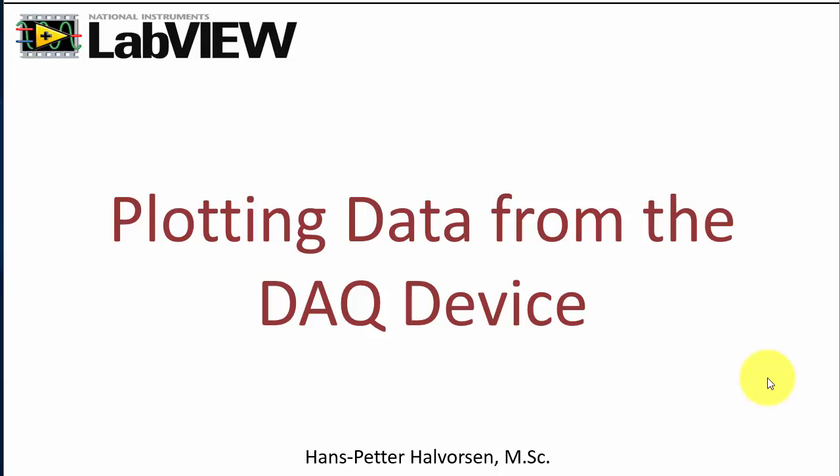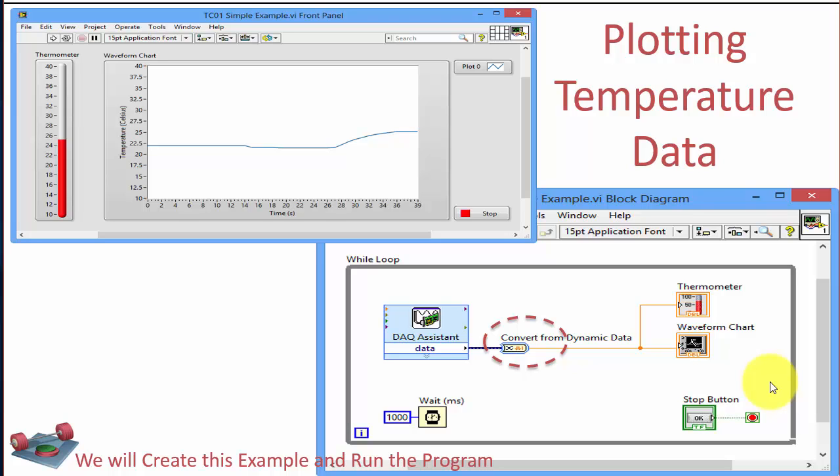Next we will learn to plot data from the DAQ device. We will learn to create this simple example. Here we have the DAQ Assistant on the block diagram. On the front panel, we have created a thermometer, which just shows the value from the DAQ device. Here we have made a waveform chart, which shows the historical data from the DAQ device. And we also have a stop button in order to stop it. So let's start to make this program.